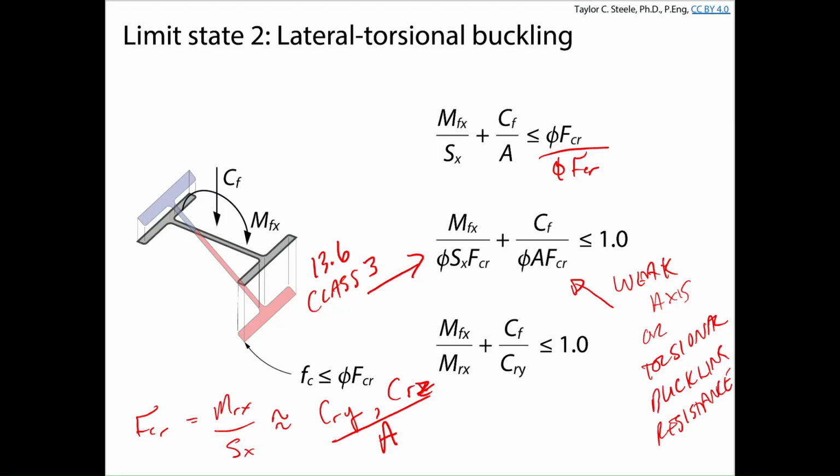95% of the time it's going to be weak axis buckling. We talked about modes of global buckling, and for wide flange sections anyway, the weak axis buckling was usually the one that was governing, even if torsional buckling was something that we would be considering. Okay, so now for lateral torsional buckling, we've got lots of compressive stress. The presence of the compression on the column makes it worse. We want to make sure that the combined stress is less than the stress that would cause either weak axis buckling of the compression flange or lateral torsional buckling of the compression flange.